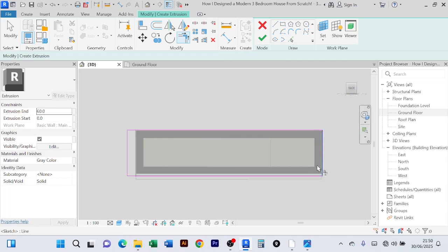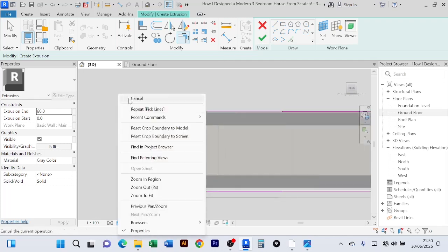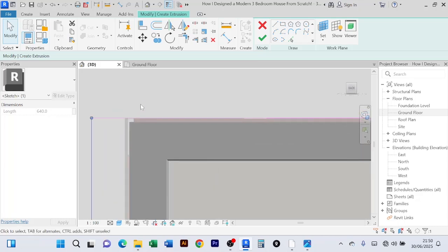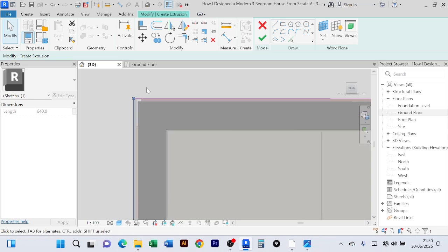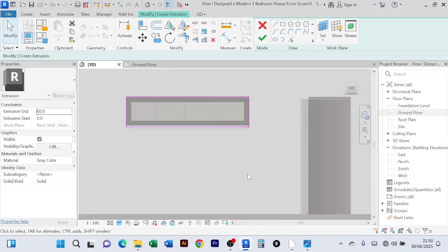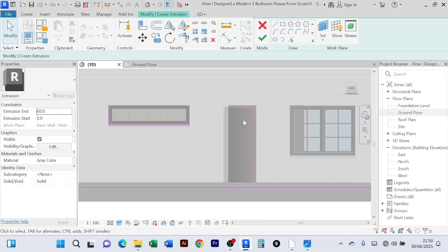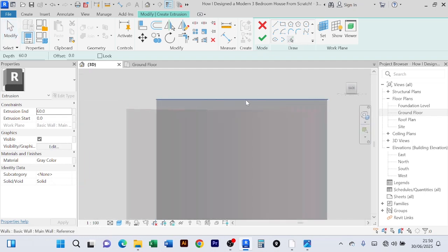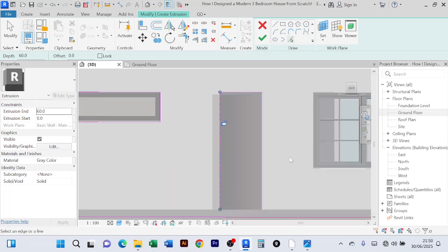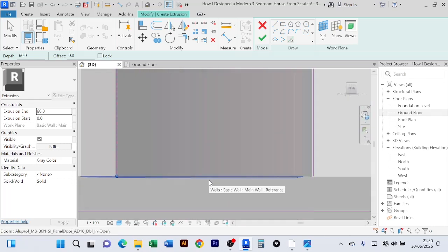However, this side is not okay. We can even drag. Instead of picking, we can also drag using the arrow keys on your keyboard. Can do that. You'll still achieve what you want to achieve. So now we need to remove this door. I'll come to pick line. I'll pick this part of the door, this one here, that line, even the downer side.